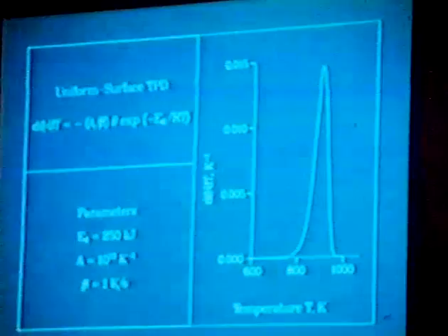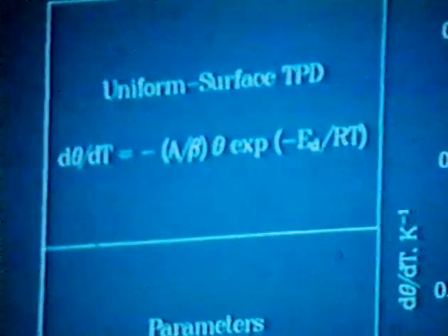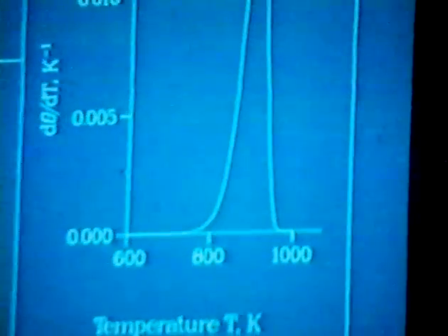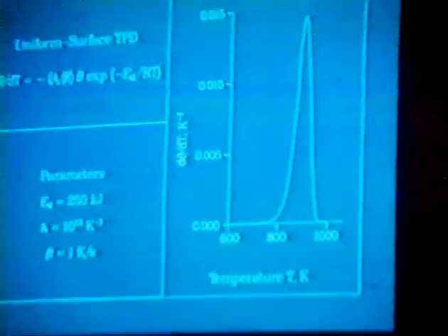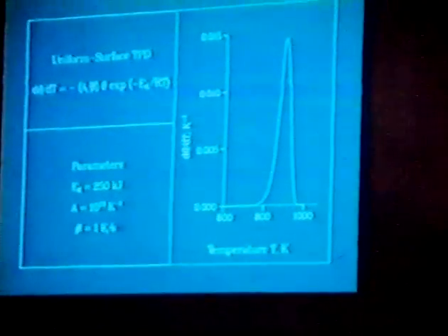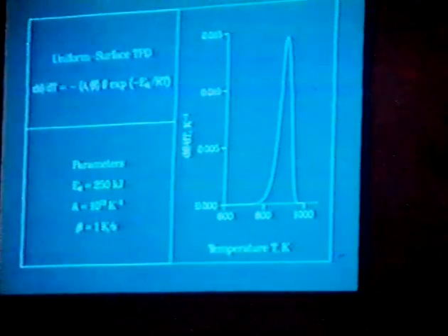What we've got here, in order to get your parameters A and E, the first developers of this technique recommended peak analysis at different heating rates, but with the advent of good nonlinear regression techniques, it turns out, you can pick sometimes as many as 100, 500 points off of this. You've got 500 points and 2 unknowns. That is a real overdetermined system. So you use just nonlinear regression to get your values of A and E.